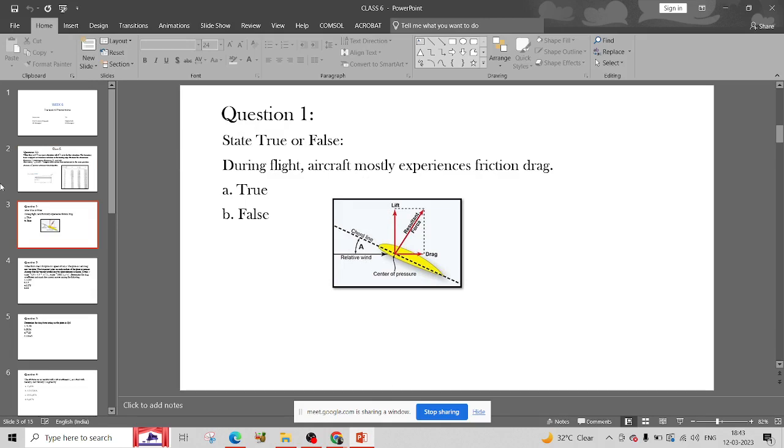So pressure drag is comparatively smaller due to the shape of the aircraft, as we can see in the diagram itself. The air flowing past an object pushes harder against the front than at the back. This difference creates a pressure drag. As the aircraft speed increases, the drag on the aircraft generally increases much faster. Doubling the speed makes the airplane encounter twice as much moving air than earlier, causing drag to quadruple.